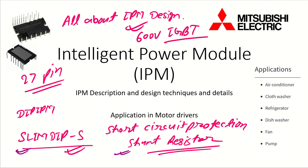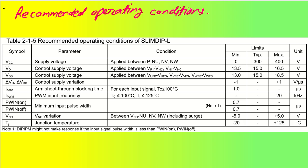So quickly we will understand what the recommended rating is for this particular IC, which is the SLIMDIP-S package. As we can see, the VCC supply voltage is typically 300 volt. The control supply voltage is 15 volt. Generally the control supplies are for the high side gate driver, low side gate driver and so on. And we have VDB, which is the control supply voltage again between these, which is again 15 volt.